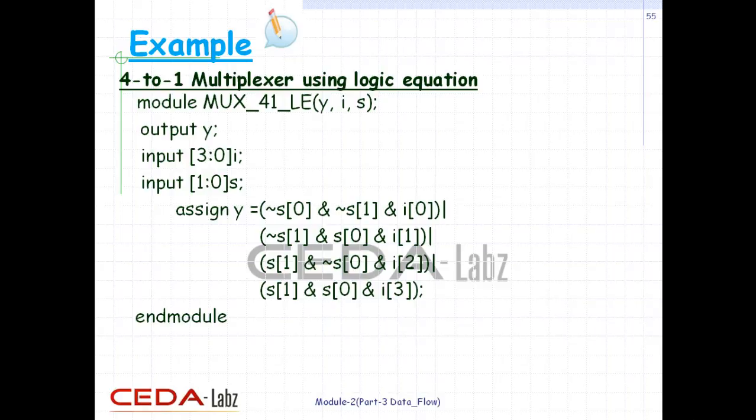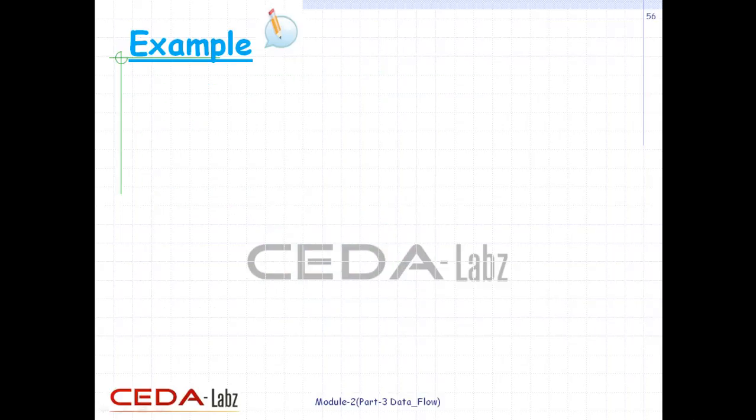Notice that everything is the same as the gate-level Verilog description, except that computation of out is done by specifying one logic equation, by using operators, instead of individual gate instantiations. Input-output ports remain the same. This is important so that the interface with the environment does not change. Only the internals of the module change. Notice how concise the description is compared to the gate-level description.